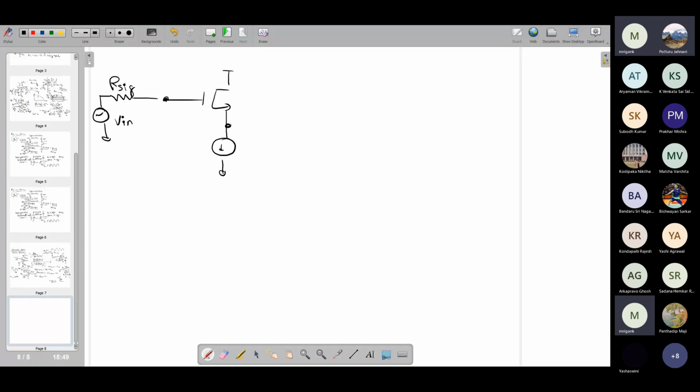And also we need to look at this particular point. As we have already seen, if the capacitive load here is large, then of course it will be a serious concern. Otherwise, if the capacitive load here is very small, we may not be very worried. Why? Because in this case, your small signal resistance at this node is just 1 upon GM, right? So if I call this R out, it is close to 1 upon GM. If you don't have a very large capacitive load, the overall RC time constant at this node may not be very large. And this may be the dominant pole.